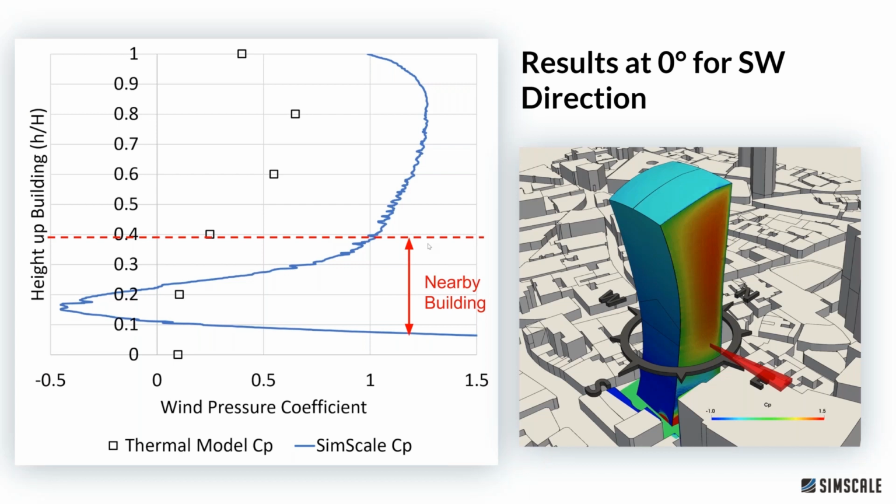Okay, and I can see some familiar names on the attendee list, so a lot of people will know what I'm talking about. When you're modeling a building in a thermal model, like TAS designed by the IES, for example, people will take a lot of time to set up the internal conditions of a building, right? So we will focus a long time and effort on internal gains, as well. You should as well. In internal gains, the fabric, the U values, what kind of equipment we're using, profiles, schedules, all of this stuff, the plant, the HVAC equipment, and that's fantastic, and we should do that.